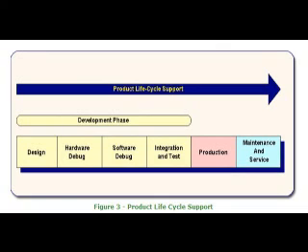Many boards include components that are assembled on both sides of the board. Most of the through holes and traces are buried and inaccessible. Loss of physical access to fine-pitched components, such as SMTs and BGAs, makes it difficult to probe the pins and distinguish between manufacturing and design problems. Often a prototype board is hurriedly built by a small assembly shop with lower quality control as compared to a production house. The prototype generally will include more assembly defects than a production unit.